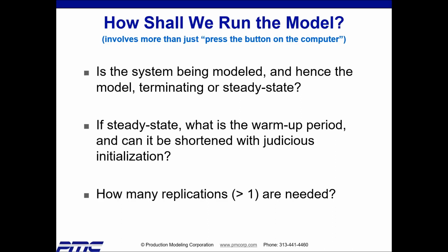So we have to tell the simulation software, use a warm-up period of 1 day or 1 week, whatever is necessary, throw those statistics away because they're biased, and then run it for a good while to get our typical long-range KPIs, key performance metrics. Now, if I go in the simulation model and put some material in some of the buffers to initialize it, maybe I don't need quite as long a warm-up time.